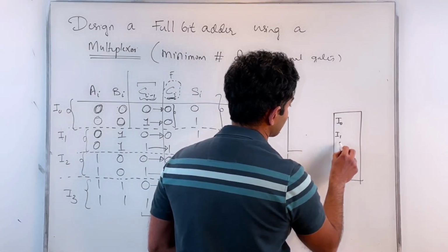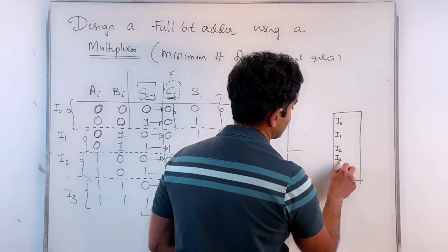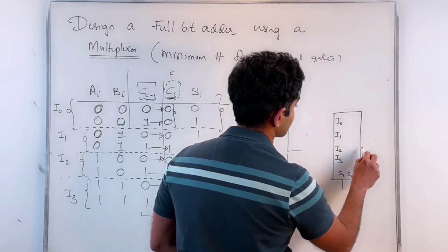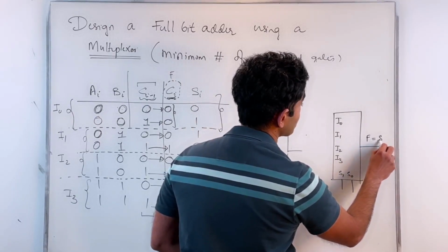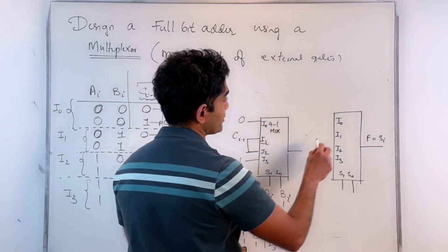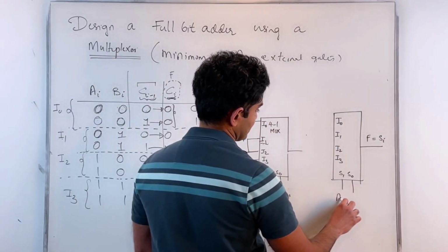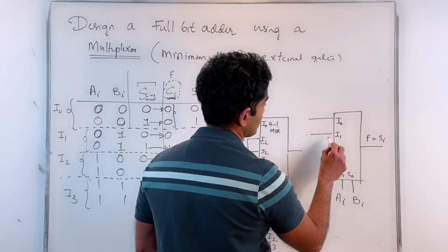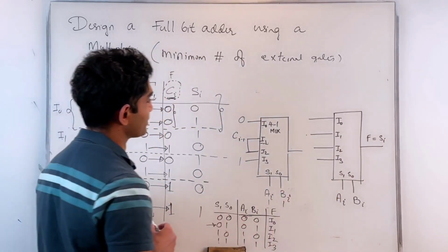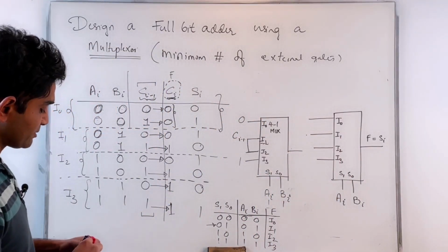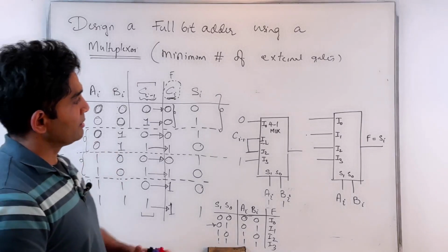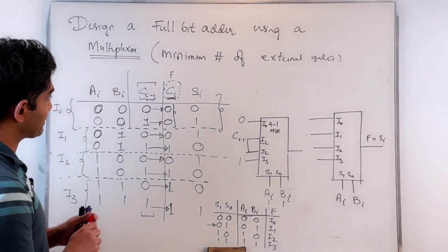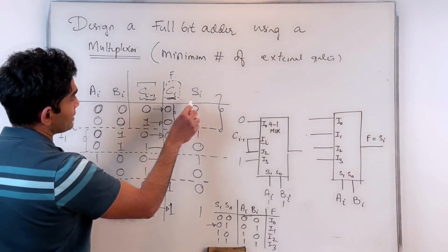That's another multiplexer we are using to obtain this Si. In this case, I'm mapping my output to the output of the multiplexer, Si. Again, to be consistent, I'm applying my Ai and Bi as my selector inputs. And now I want to obtain my Si. So in this case, again, I0 through I3 are functions only of Ci minus 1 now.